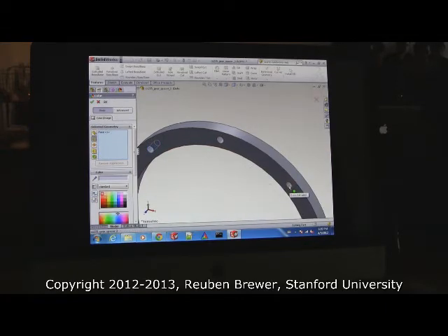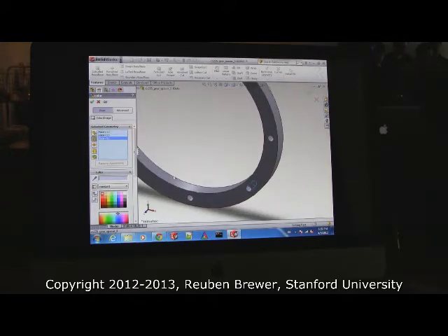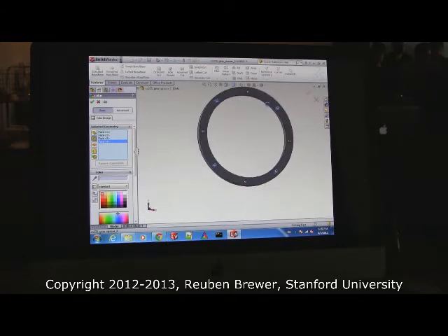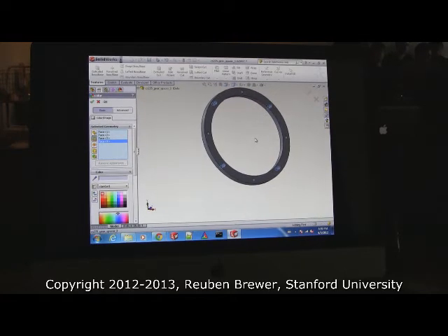And you see how it pops up Face 1 in the left hand? That's a list of different things that you're about to color. So I want you to select all 4 of those little holes. These are the press fit holes. Okay? And now on your solid model, you'll see there are 3 light blue ones. That just means they're all selected. Everybody got that?